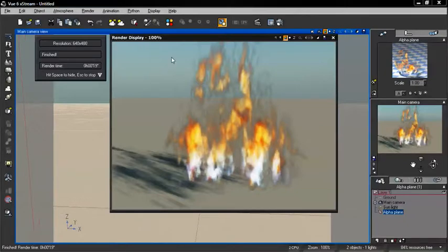And if we were using something other than a spectral model, it would render even faster. Because images are basically already rendered, and all it really needs to do is just process the information on whatever objects we have. The only real calculations it needs to consider is the luminous value along with our transparency and alpha. Now we can notice a few artifacts in here where we have some black areas showing up where it doesn't quite look correct. So what we need to do is set up a filter for this transparency in order for it to look correct.